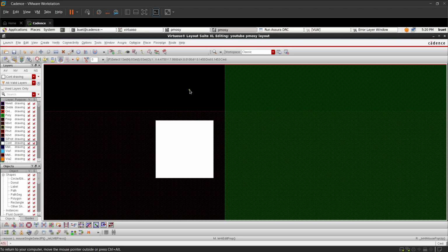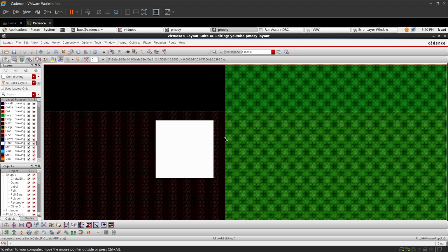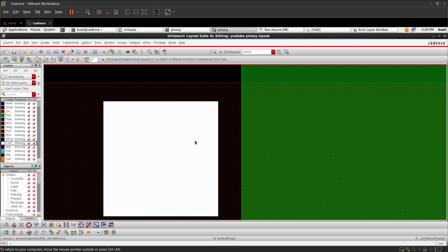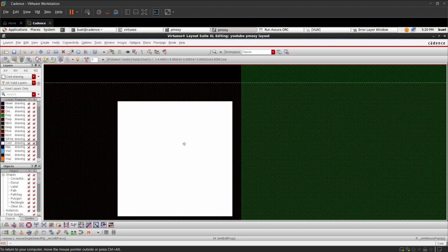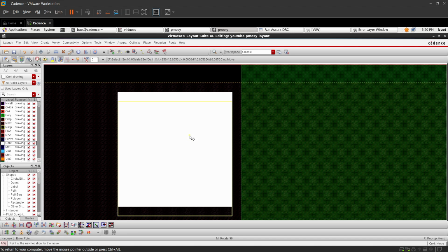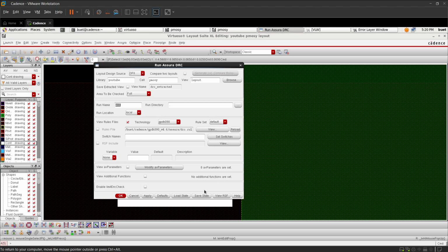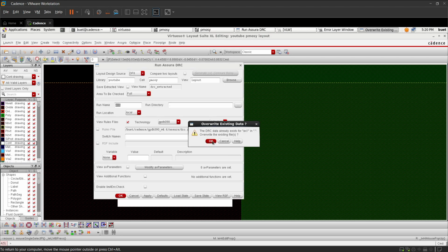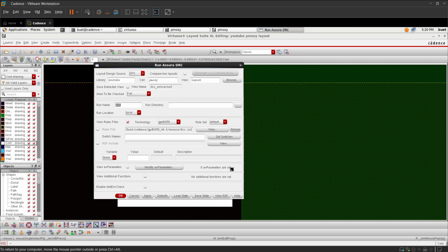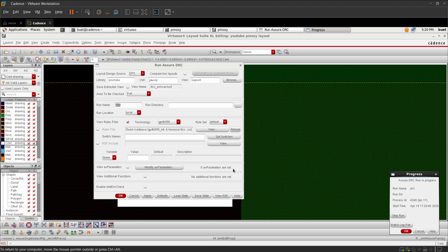Next thing you are supposed to see is what should be the spacing between the gate and your contacts. Right now we are supposed to keep it as close as possible and just save, because we are going to see what this space should be. If you want to see what this space should be, you just place your contact near the edge of oxide and poly. This is acting as a plate. Next, save and run our DRC. Just click on apply. Okay, yes. Once you have done that, it will show some errors.